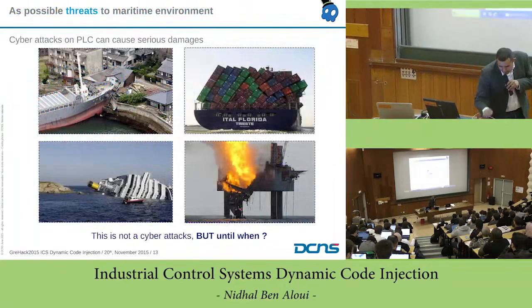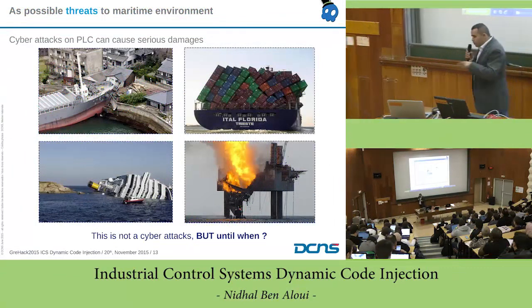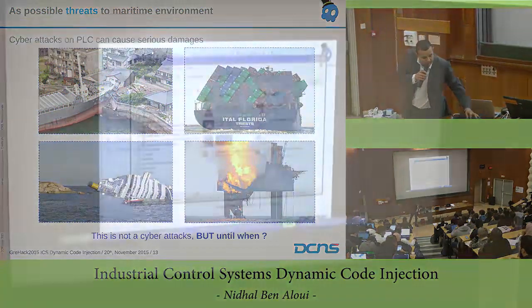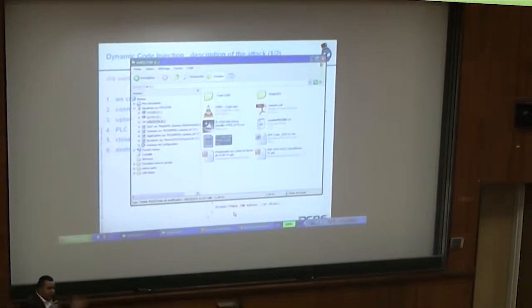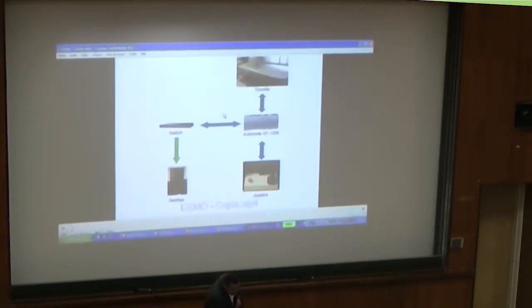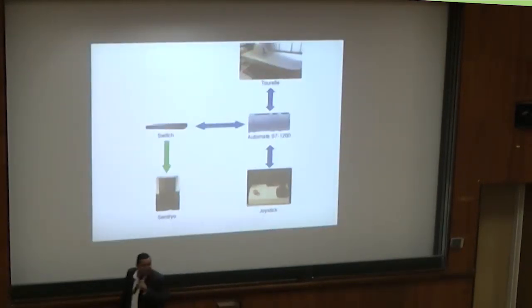So I just want to show you a video, because the equipment doesn't work, in which we make this attack. In the same video, we propose some countermeasures and protection to detect this kind of injection throughout the memory. You can also detect if there is a packet in which the hacker tries to brute force the password or change the password, using a probe like Suricata or Sentryo. Because our objective is to protect the installation, not to hack the installation.